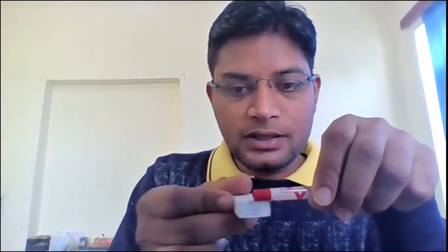But when I'm talking about a flat surface, this is a flat surface also, right? If we go for a facing operation, then this is the turning, as I mentioned in the last class, and this is facing when we are moving towards the center. So this is the turning, in this direction I'm moving, and toward this side when I'm moving, this face will come in contact with the workpiece and remove the material.